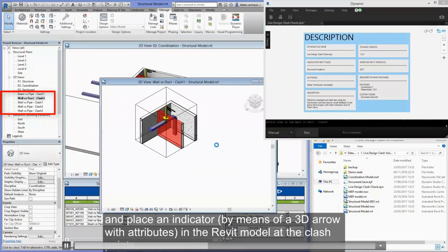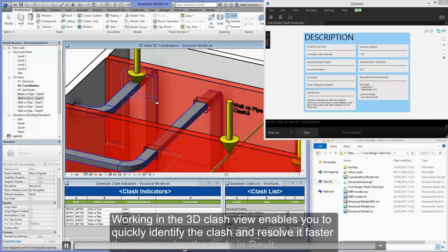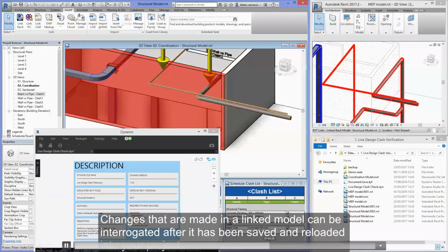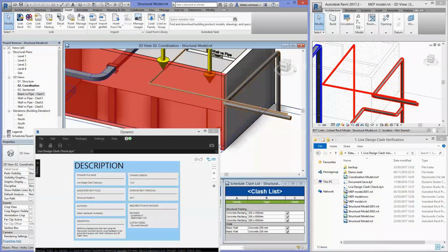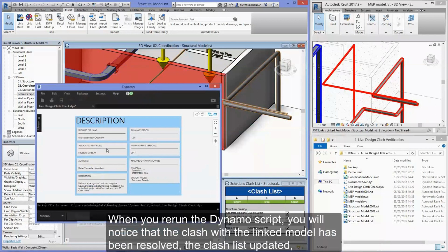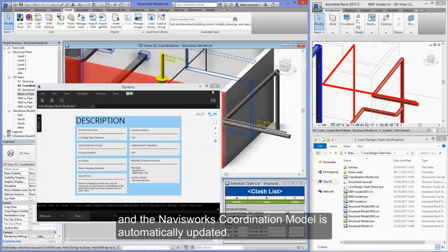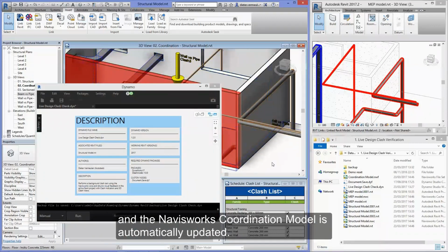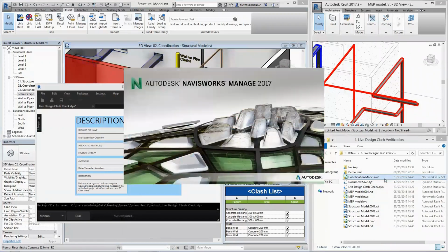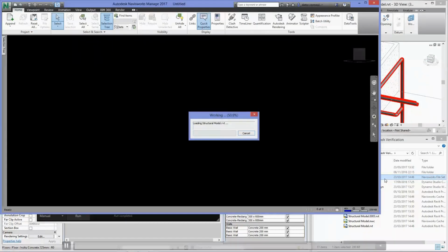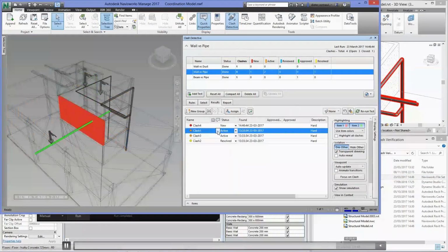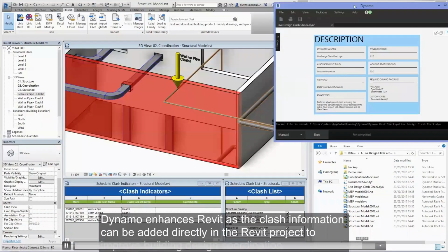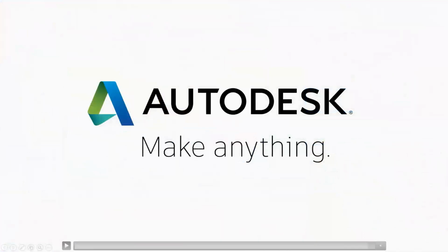And you can imagine performing this across a whole building design, and you mightn't be able to see certain parts of building designs as well. And then it allows you to create your cut opes as well. And then placing those cut opes, again, using Revit, you can schedule out those cutting opes as well. So might even for your fire consultant or your fireproofing, you know at those cut opes you need to put certain fire stopping installations as well. And again, doing the round trip by going back into Navisworks as well, and checking if those clashes have been cleared also. So that's looking at using some Dynamo.